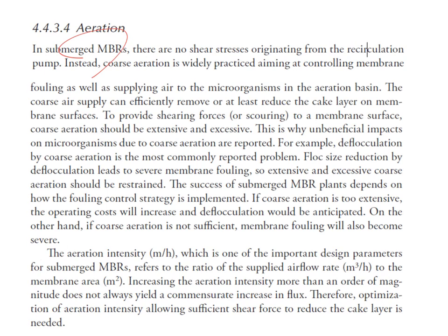Instead, we have selective shear stress near the membrane surface, which is created by this aeration. So this aeration is very important in preventing membrane fouling in these submerged membrane systems, submerged MBR.